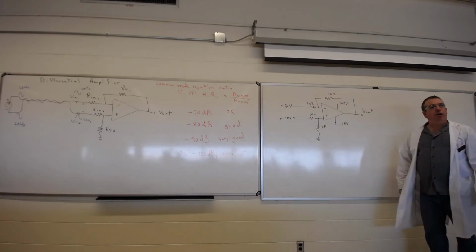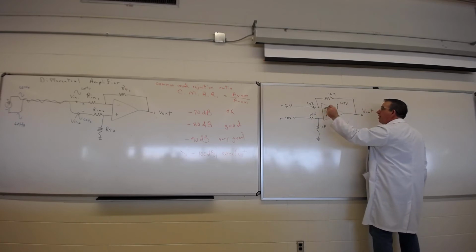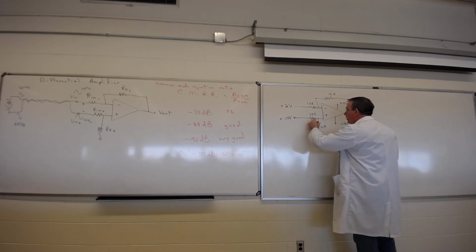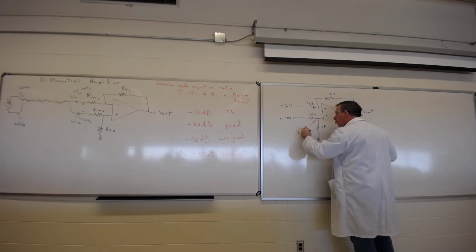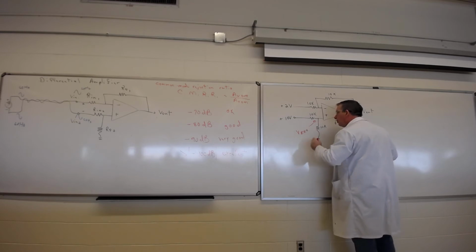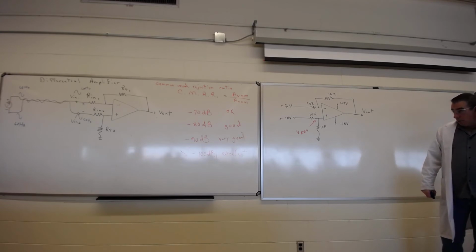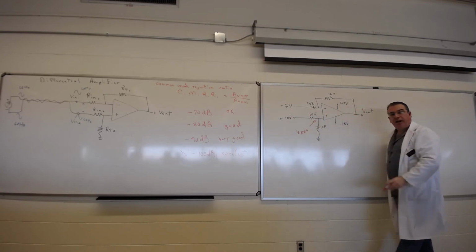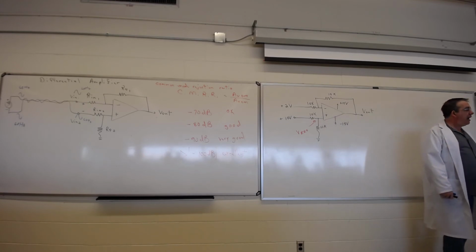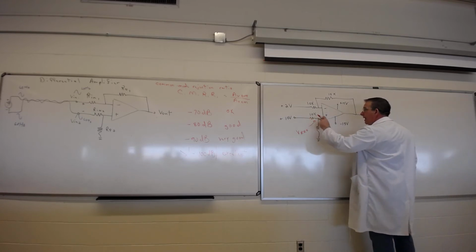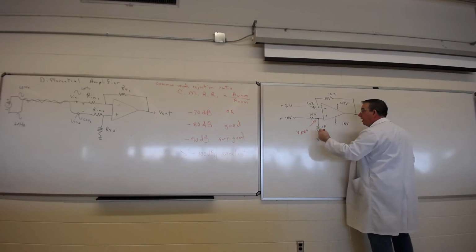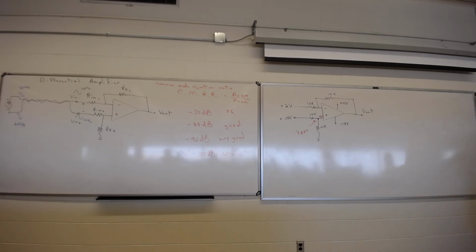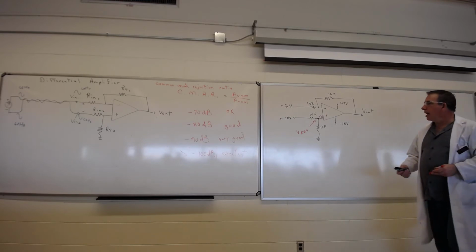All right. So again, like I said, we've got negative feedback, and that's the output trying to make the negative input the same voltage as the positive input. So let's go to the positive input and see what the reference voltage is. This thing right here, going into here, we can think of as V reference. So look carefully. I've got 2 resistors here, 10 volts at the top, ground over here. This thing is a voltage divider because we have no current going into the amplifier. We know that. So if I have 10 volts, 10K and 10K, it would only make sense if the voltage right at this input from here to ground would be 5 volts. 2 10K resistors split up the voltage equally. There you go. So that's the reference voltage on one side. This is just a simple voltage divider.